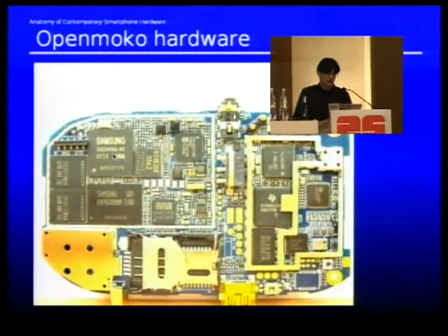We have the system on a chip here. This is the one which does not have the integrated flash and SDRAM. So we have the flash here, SDRAM here. And the S-Media here is the graphics accelerator. This one, the PCF50633, is the power management unit, which is the same that is used in the iPhone, by the way. We made NXP open the datasheet, so I'm sure people can have creative uses for that. That's the Wolfson codec for the audio side, and that one, I think, is the audio amplifier over there.